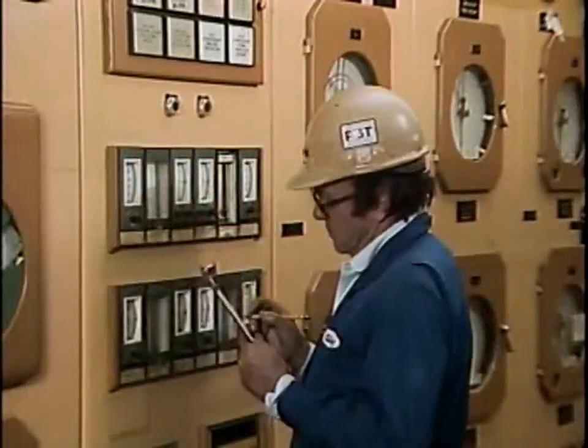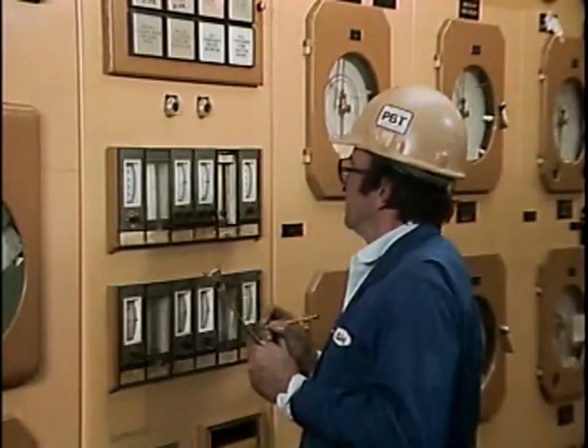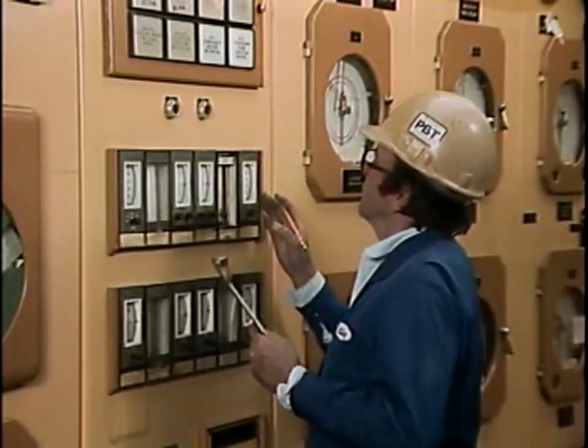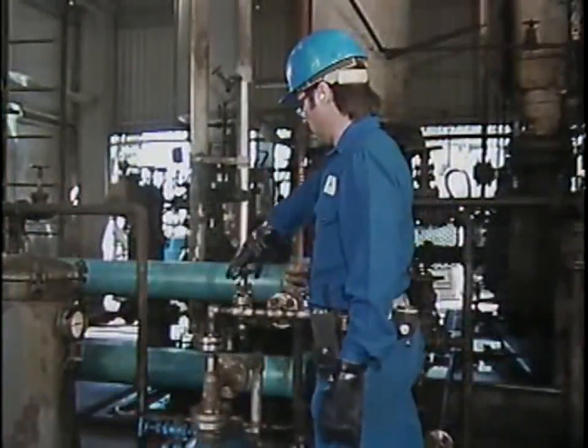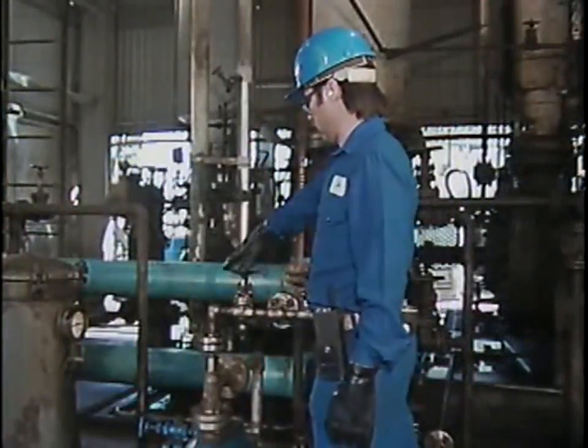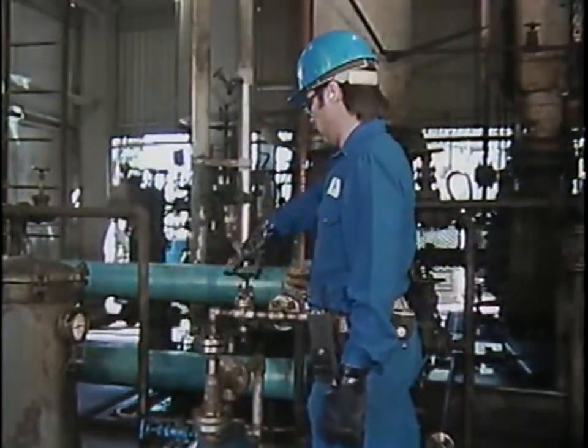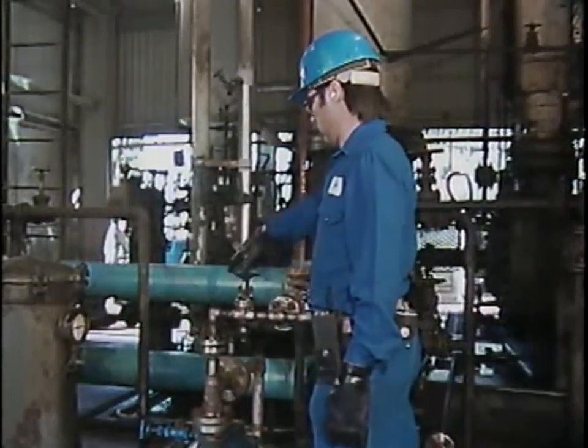Keeping an eye on instrument readings is also important because they can tell you when problems are developing. After the gas flow has completely stopped and the compressor is no longer rotating, the compressor auxiliaries can be taken out of service. In this topic, we looked at compressor operation by focusing on startup, normal operation, and shutdown. Try some practice questions now that relate to this material.